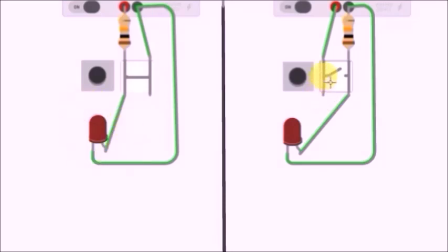On the other side, we have the same button, but the positive voltage is connected to nothing. When the button is pushed, we have current flowing, and the resistor allows to obstruct the way to the current so that it flows rather to the LED. As the button has a small size, it is sensitive to interferences caused by surrounding objects and can give false information. The resistors avoid this effect.